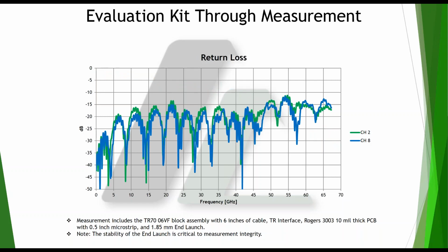Again, you can see that this is our return loss that we're pulling from this first measurement. Again, the variance starts to waver a little bit after 40 gigahertz. Again, this can be a PCB and trace problem. And sure, we'll look at this a little bit more as we de-embed the connector from these measurements.